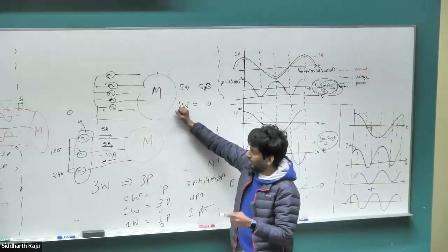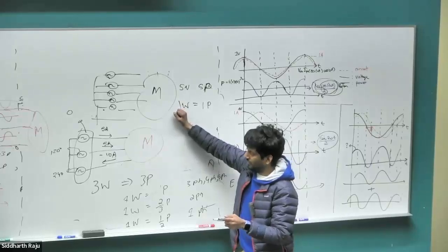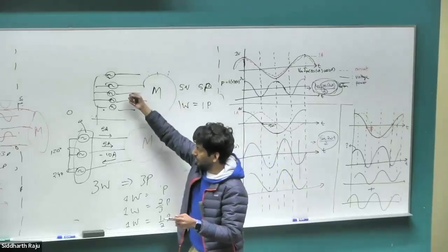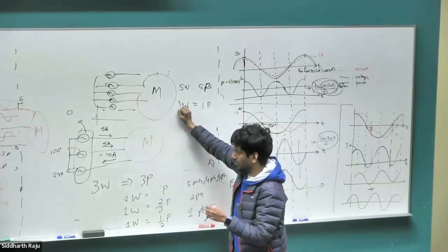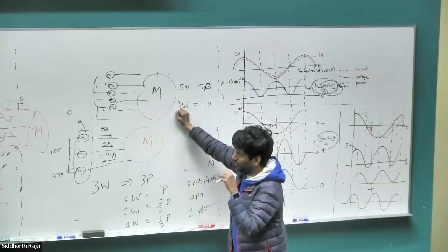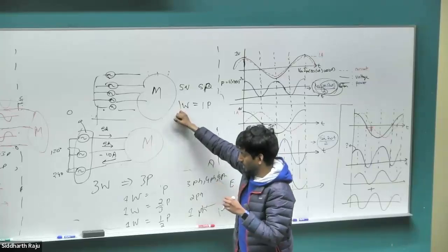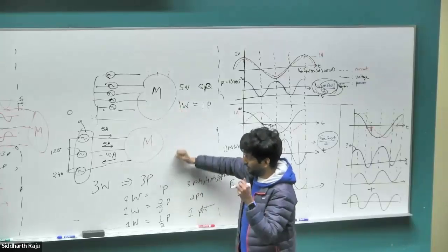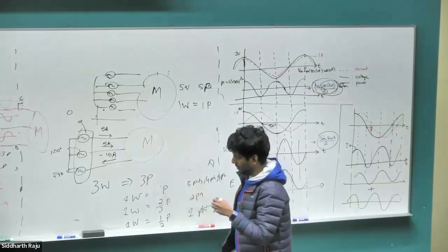In EV applications, you do create 5-phase motors because they give you some amount of redundancy. One phase fails and you can still control the motor using the other 4 phases. In 6-phase, typically used, one phase fails, you can still use the other set of phases with reduced power. And the other advantage is you can remove torque pulsation by selecting the correct set of windings. But for power transmission, 3-phase is the one that makes the most sense.